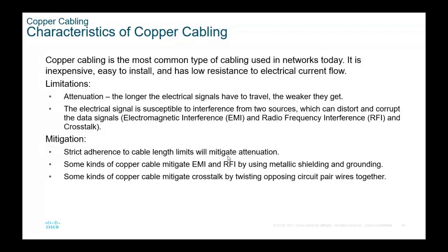So it's susceptible to EM interference, radio frequency interference and crosstalk. Crosstalk is where, as you pass electricity through these cables, there's actually an electromagnetic field around the cables, and that electromagnetic field could interfere with the current of another cable.